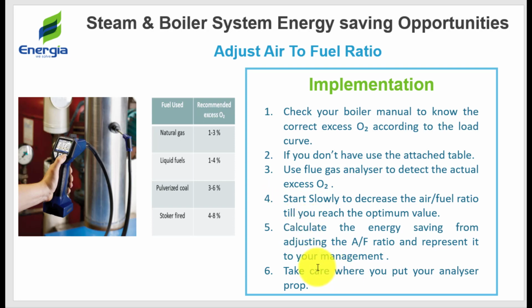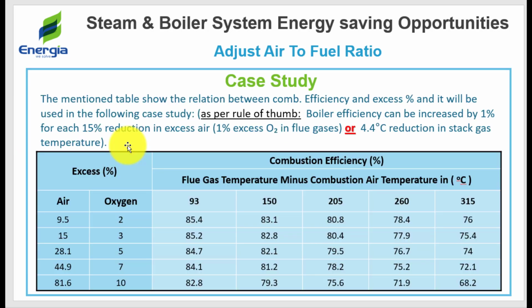And then take care when you are making this one, you have to make it in small steps, and then also you need to take care where you put your analyzer probe in order to have a proper measurement for the amount of oxygen that you have. Let's take one case study to see how this really economically reflects on your operating cost.